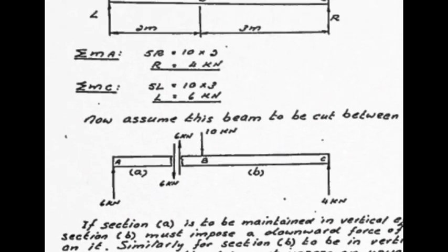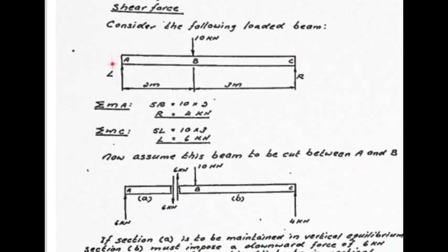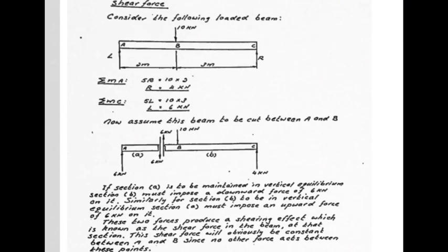This beam, as it stands over here loaded with these 3 forces, is feeling shear all along its length, and at this point where we are now focusing, it is experiencing 6 kilonewtons of shearing action. In fact, everywhere from A all the way through to B, all places along this particular beam are feeling that very same shearing effect.